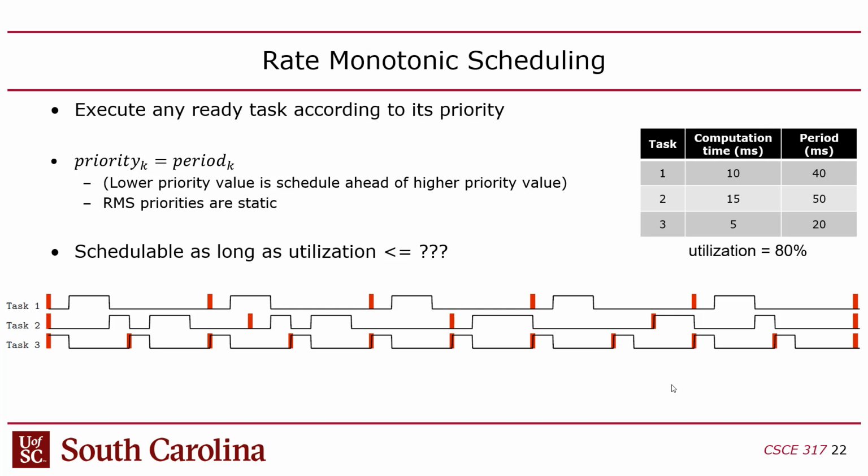The problem is that it's a little bit difficult to tell when a task ends, because you'll notice this task 2 starts here and then it goes dead, right? But why? Because it got preempted, right? But then it comes back here, it picks up where it left off, and then it goes dead here again. Why? Because it finished, right? So task 2 stopped here because of preemption and it stopped here because it finished, and the timing diagram doesn't indicate the difference. Actually, I could have color-coded it or something. But yeah, that's what's happening there.